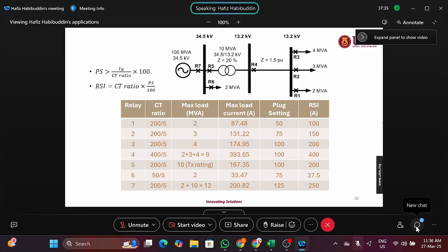Check your calculation against this value. The relay setting current is going to be greater than this. Again, this is the transformer. Whether it is greater or lower than this depends on your justification, to allow overload or not, and so on.